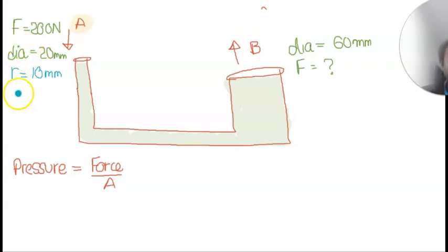So we will use the formula pi r square. Now remember, this radius is actually in millimeter. If you want to convert straight away into meters, you can, but when we get the pressure, I can convert straight into megapascal. So we can do it that way as well. So find the area.